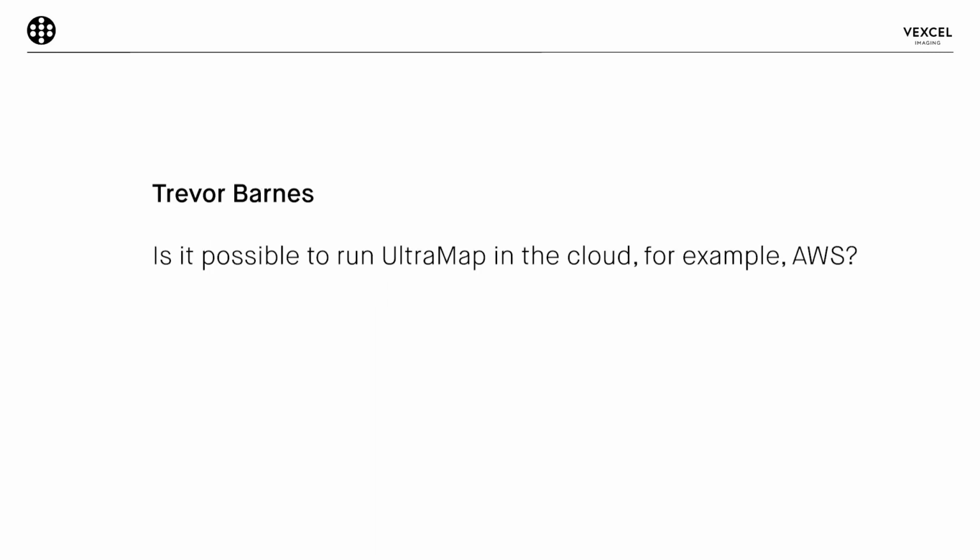Great, thanks. Is it possible to run UltraMap in the cloud, for example, AWS? Well, right now, UltraMap does not yet officially support processing in the cloud. We still require a dongle on a USB key, and that dongle needs to be attached to a coordinator. So you somehow need to have access to a USB port in the cloud, or to a PC that interacts with the cloud, that allows to hold this key.